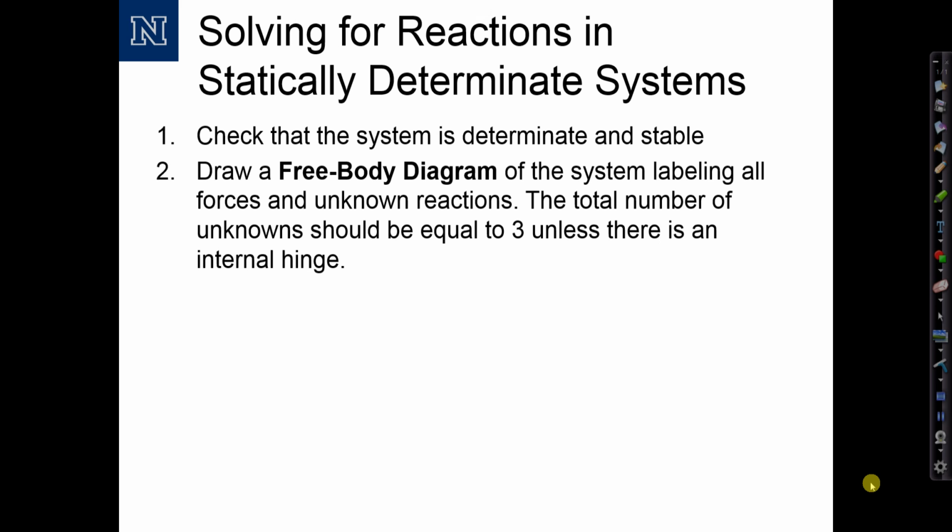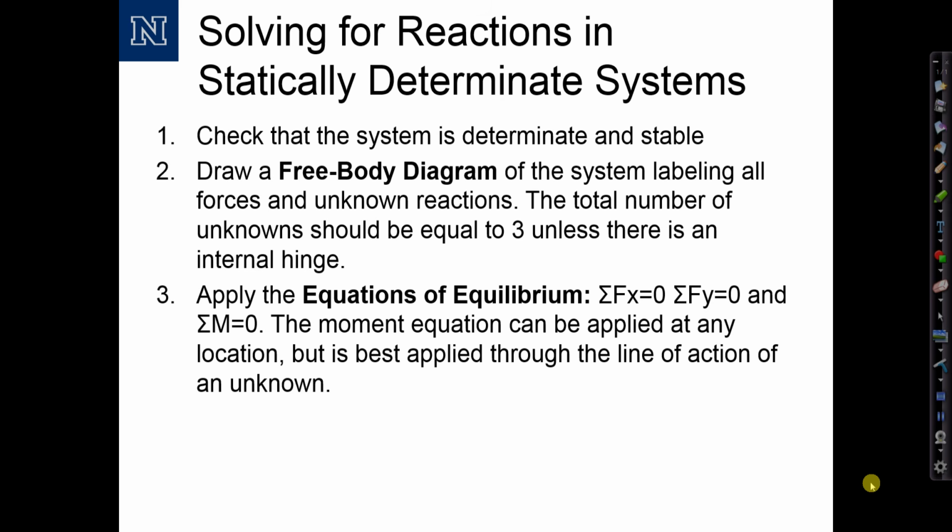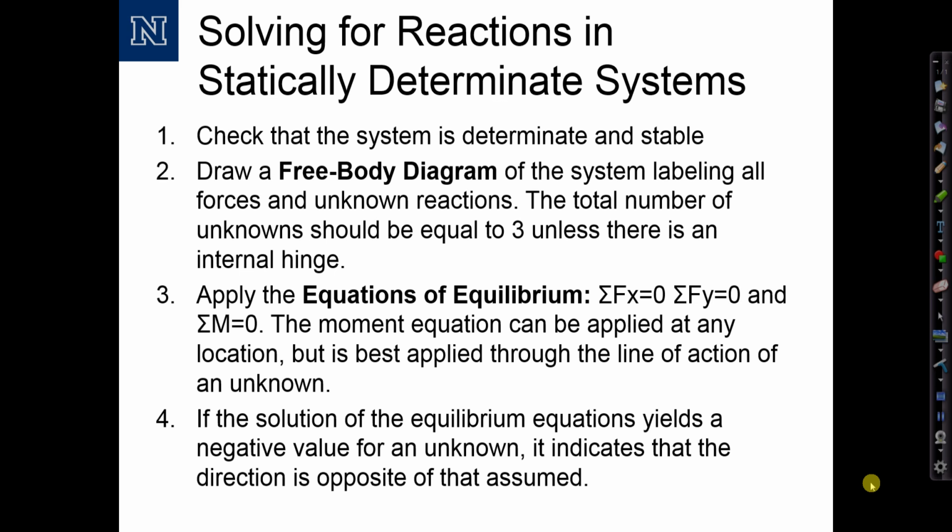Second, we draw a free body diagram of the system labeling all forces and unknown reactions. Third, we apply the equations of equilibrium. Note that the moment equation can be applied at any location, but is best applied through the line of action of an unknown, and we will demonstrate that.